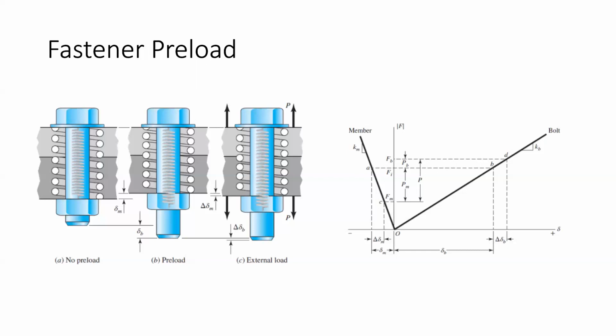But that's a good question. What do you do when the two materials are different? Basically, you just get a different friction coefficient between the two materials, and the weaker material, in this case I think it's the nut, just fails first, right? So you preload to whatever amount of proof load the nut can handle. Good question about exactly what you're talking about.